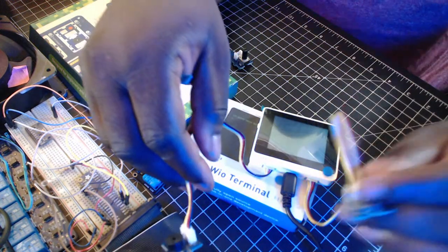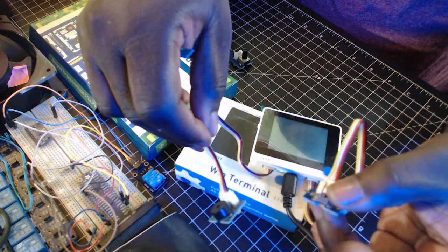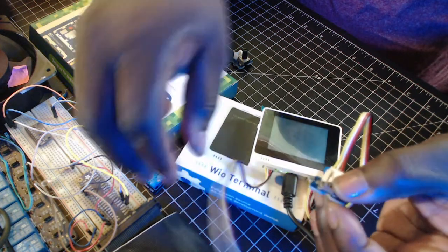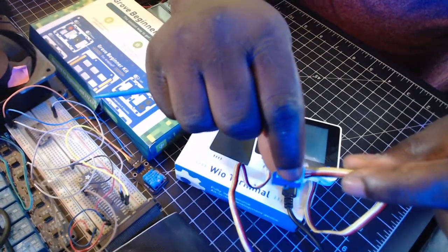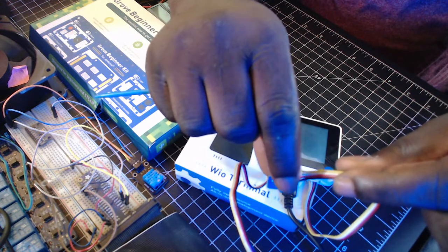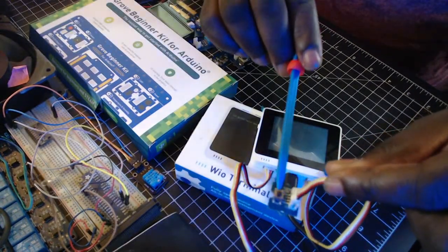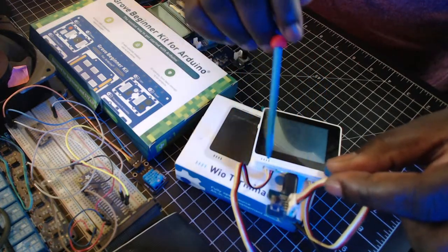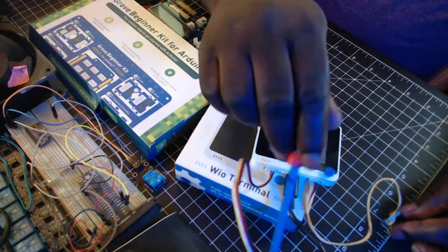And the simple code is that anytime I press this button, you see that the buzzer goes off. I don't know if you can hear the buzzer, but yes, anytime I press it, the buzzer goes off. So that's very basic because now I've connected the button to digital 0 on the Wio Terminal, and I have forced this I2C to also be seen as a digital pin that's controlling the buzzer.